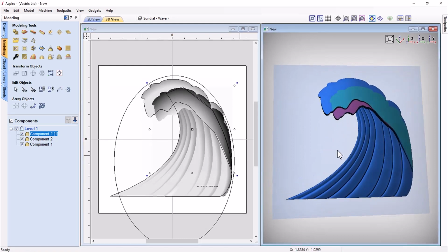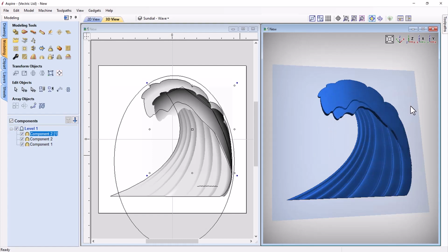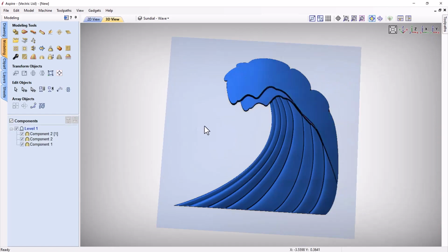And now if I want to adjust my shape height, I can choose this in the 3D view, and these new handles come up that we can adjust, our shape height or our base height. Base height would be dragging the cube, and the shape height is dragging the arrow. For this case, I'm going to grab the shape height, and I can size it and put it right where I want it to be. I get instant feedback now, where before in version 11 we didn't have that at all. And that looks great to start out with. So let's just go ahead and maximize this for a second and have a look at what we have.